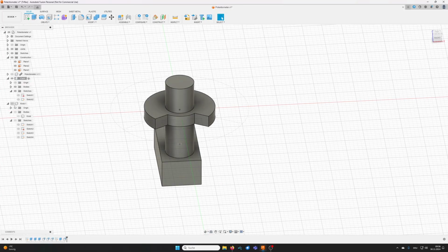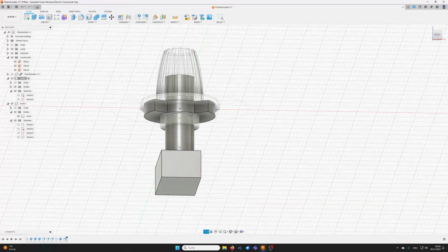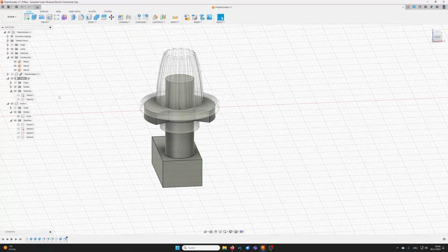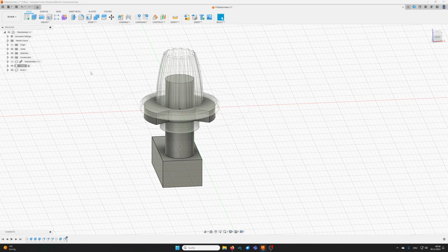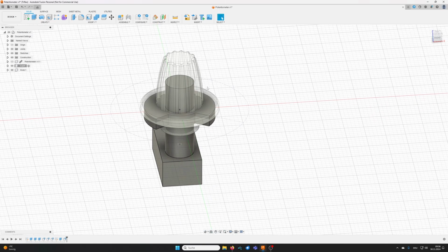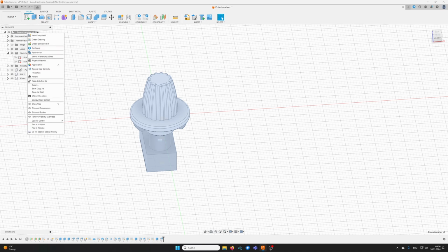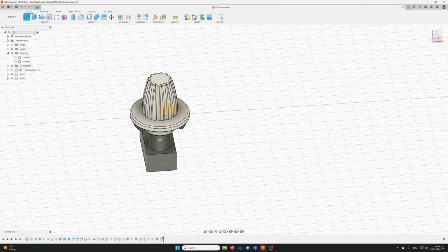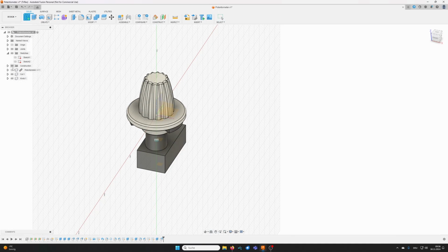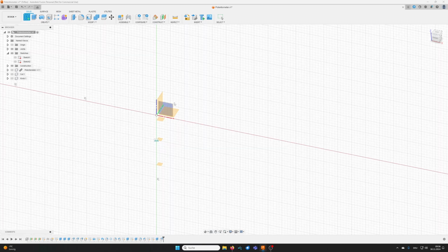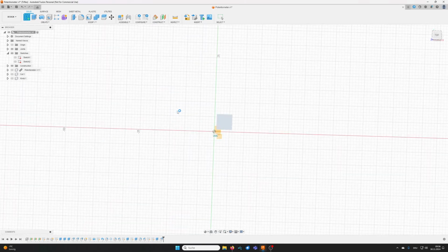Okay, let's have a look. The knob, the potentiometer, the cut body. Then it's time to create the label or the sketch with our labels. For this, go to the main component and create a sketch on the top face.